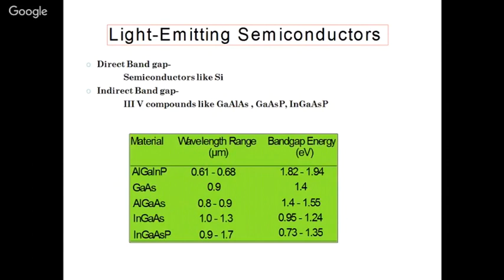And then indium gallium arsenide could give us, I'll say, 1000 nanometers to 1300 nanometers. And then fiber is even better if we go to 1500 nanometers or to 1800. So there are light sources which can give you that with indium gallium arsenide phosphide.